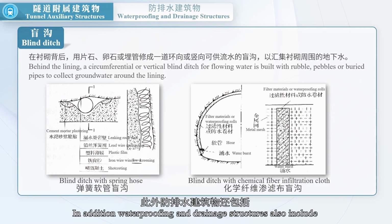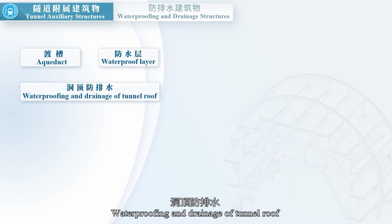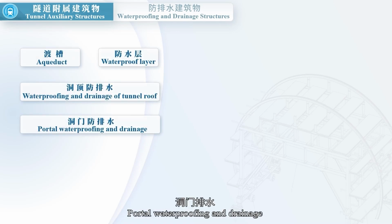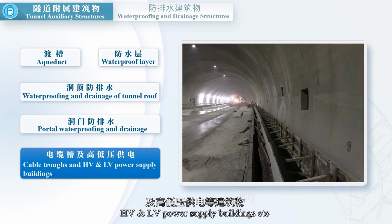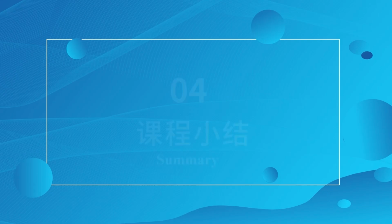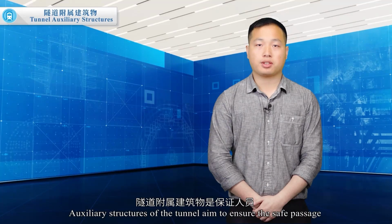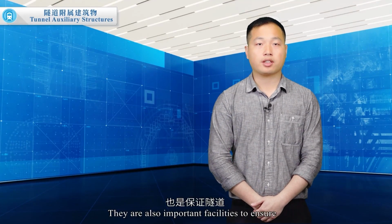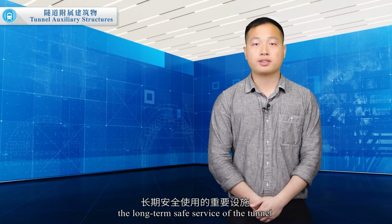In addition, waterproofing and drainage structures also include aqueduct, waterproof layer, waterproofing and drainage of tunnel roof, and portal waterproofing and drainage. Finally, the tunnel auxiliary structures also include cable troughs, HV and LV power supply buildings, etc. Auxiliary structures of the tunnel aim to ensure the safe passage of personnel and vehicles. They are also important facilities to ensure the long-term safe service of the tunnel.